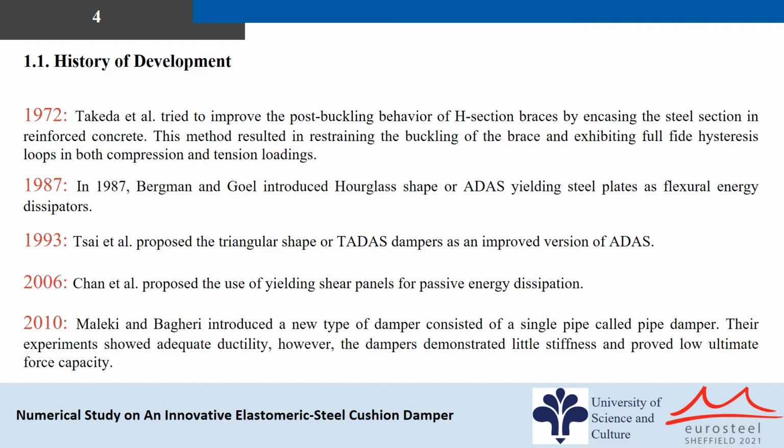In 1987, Bergman and Goel introduced hourglass shape or ADAS yielding steel plates as flexural energy dissipators. In 1993, Tsai et al. proposed the triangular shape or TADAS dampers as an improved version of ADAS. In 2006, Chen et al. proposed the use of yield shear panels for passive energy dissipation.